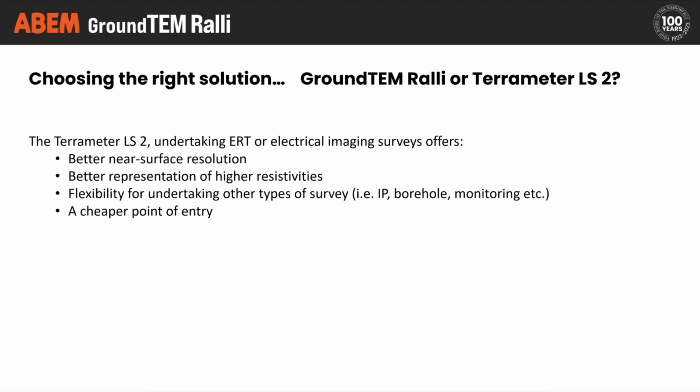So in general, ERT systems provide better near-surface resolution. Your electrodes are plugged into the ground, so you can get good detail almost immediately from that system. We have much better representation of higher resistivities with an ERT system.